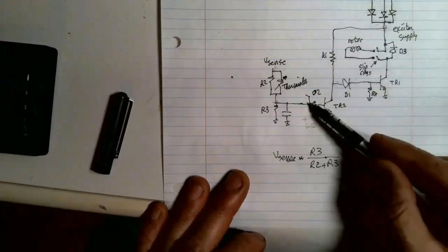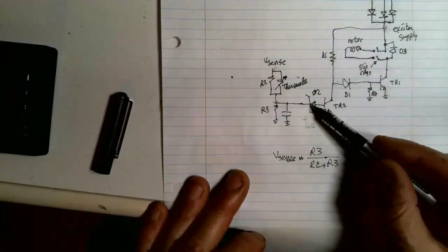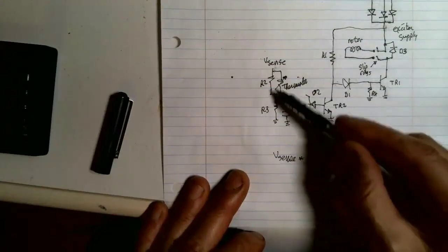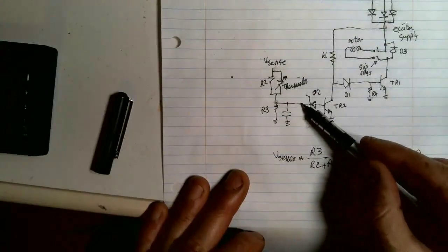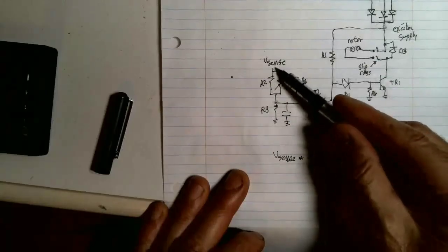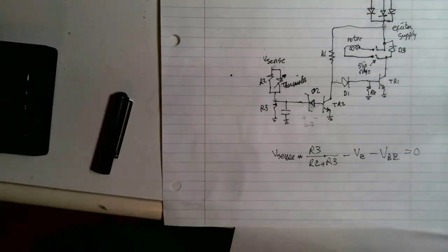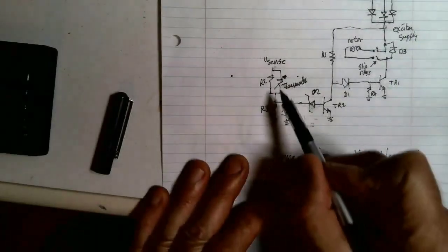Again, 0.7 plus 6.2, that's a 6.2 volt zener, that's 6.9 volts. And then what do you have to have here to get 6.9 volts here? Well, if it's a 2-to-1 voltage divider, you need 13.8 volts here. So that is how this regulator works, kind of, because we can't really calculate it since I don't have values here. All right, that's where it starts regulating.